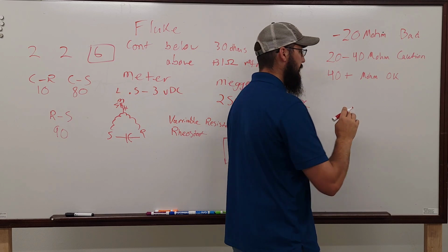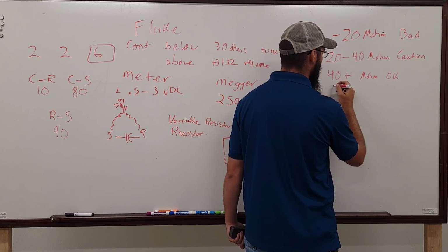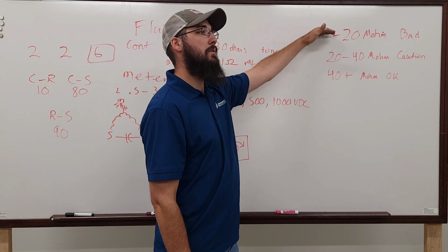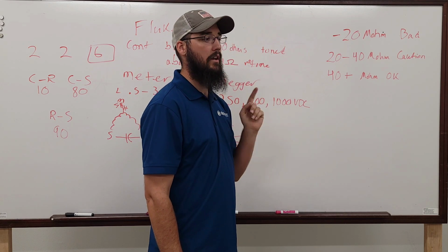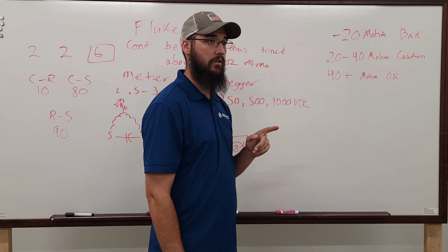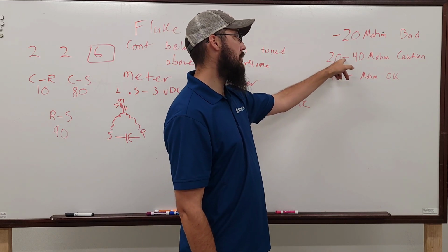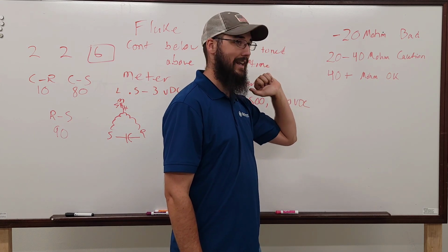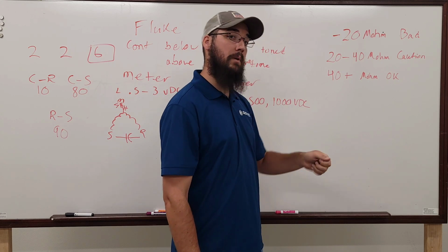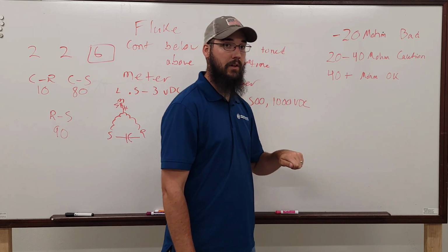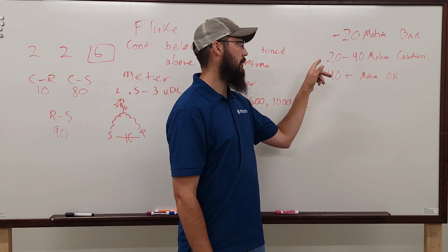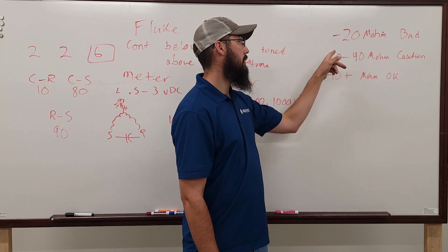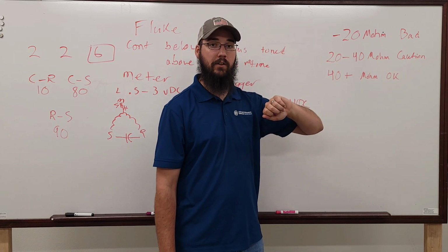Ideally, your Megger will peg out at OL every time to ground. By the time you hit 20 million and less, you may or may not get that motor to run on a starter. Typically by the time you get below 30, hitting 20, and especially below 20 million, a VFD will likely not run. You might be able to put it in bypass, and it might run in bypass, but the VFD is going to trip on overcurrent or ground fault specifically. It'll probably trip on a ground fault, even though the bypass side of the drive will actually let it run.